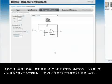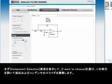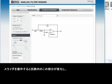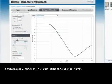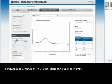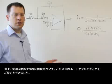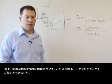So I just wanted to jump in here quickly and show you how to make this resistor-capacitor trade-off with our tool. So you'd go to the component selection screen, choose I want to choose, open this accordion, and adjust these resistors and capacitor slider. So you can see them changing here in the circuit. Then you can see the effect, say, on the magnitude as we change it, or say on the noise. So that's 1 degree of freedom that we can use, and we give you the option of doing that trade-off.